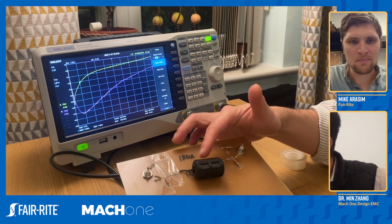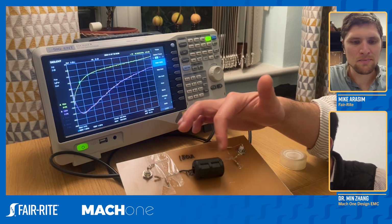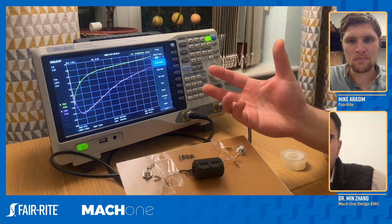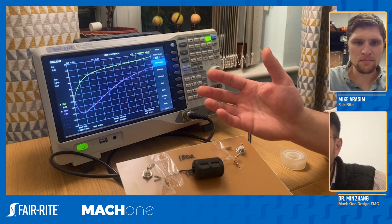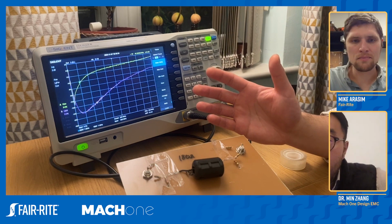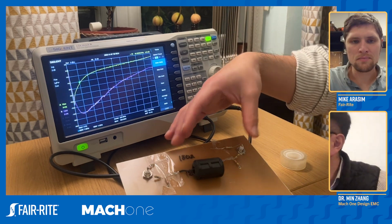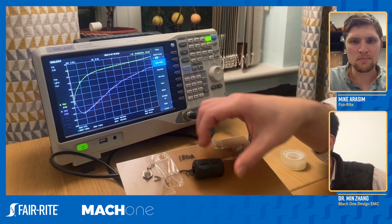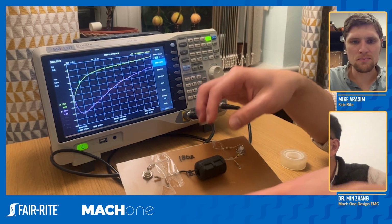Therefore, the wire length, being a few inches long, introduces about 60 to 80 nanohenry of inductance. You can work out that at 400 and 500 megahertz, its impedance actually dominates. So we definitely need to normalize that out.